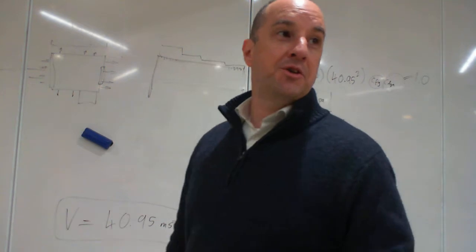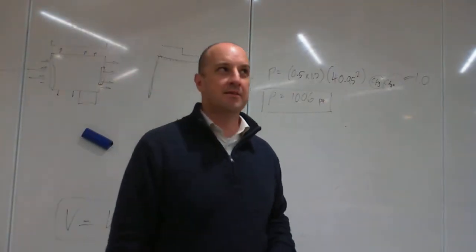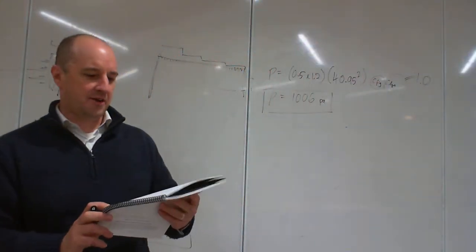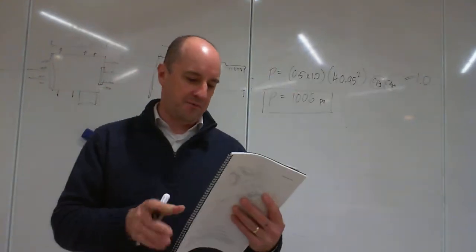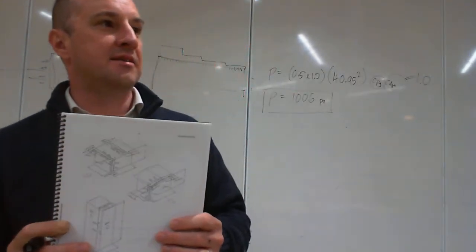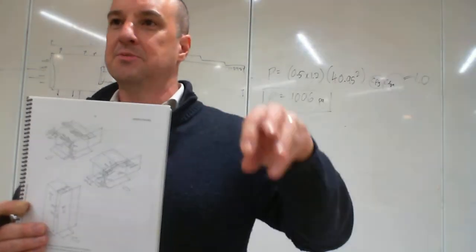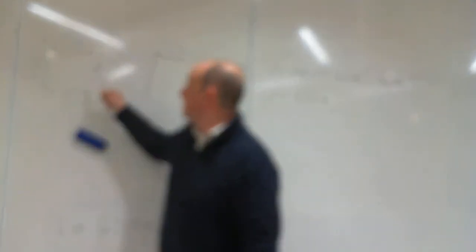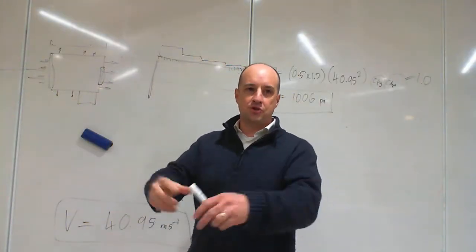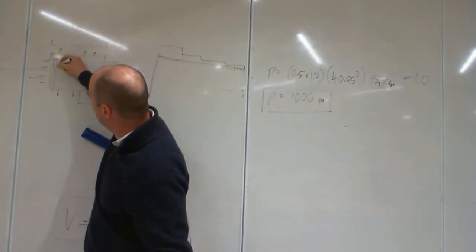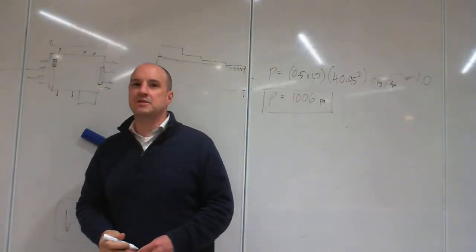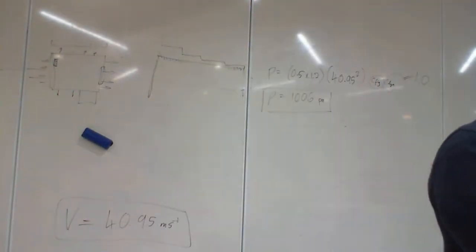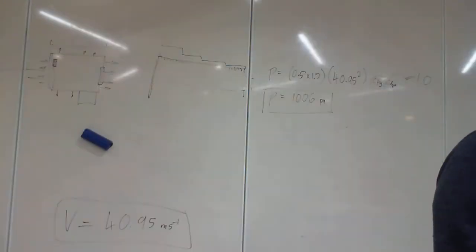The next little nightmare, which you don't have to deal with right now for your wall, but maybe you do, is called local pressure factors. Okay? This is the second half of Chapter 5. What it's talking about is that the wind acts harder in a small area, and you can average it out a bit on a larger area. Up until now, we've talked about the wind on the whole roof. Now you have to zoom in and say, on a small area, you can actually get an effect which is higher than the pressure we're talking about. It can be 1.5 times as much. It can even be, in certain configurations, 3 times as much.